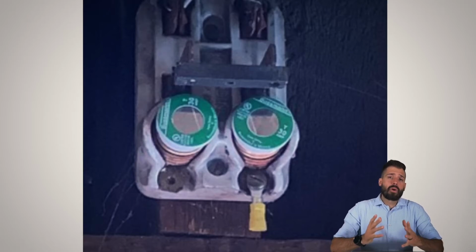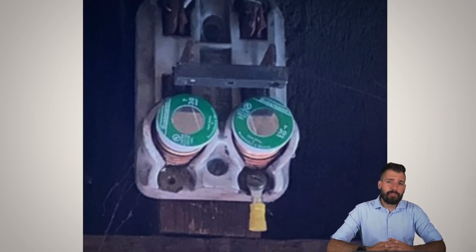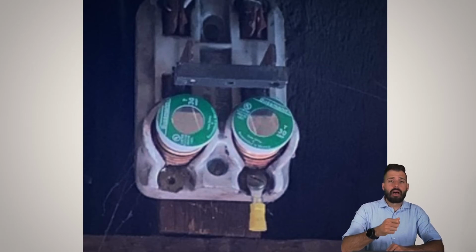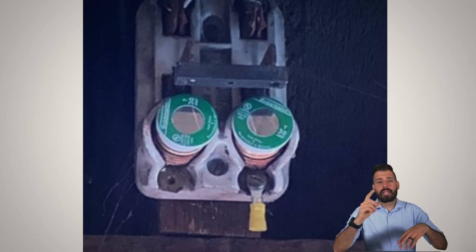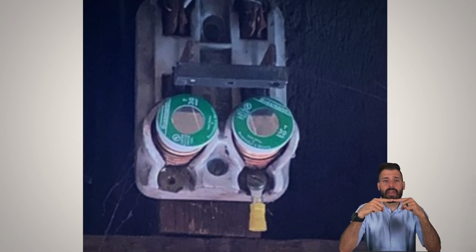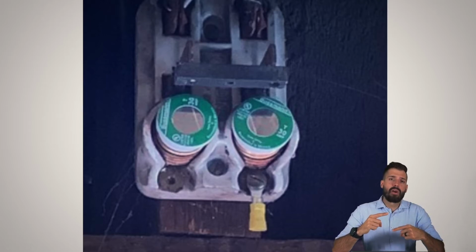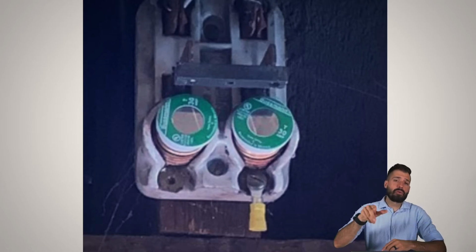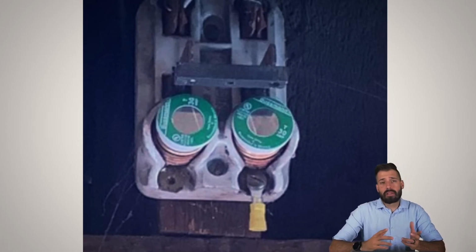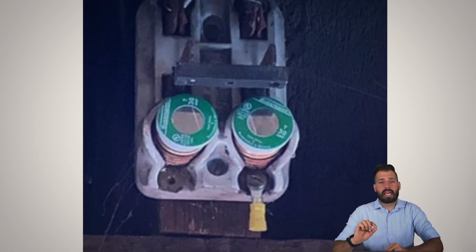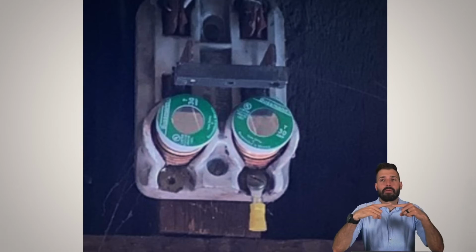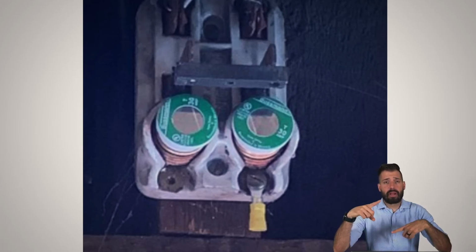With these fuses, the way that a fuse works, remember we were talking about a circuit breaker, it will shut off before any of the wires get too hot. Well, inside of here, you have a wire, and whenever that wire gets too hot, the wire will break. Whenever that wire breaks, you then have to unscrew, just like a light bulb, that fuse and then screw it back in. Whenever you do that, then we're good to go. So they've basically put a sacrificial piece of wire that will just break whenever it gets too hot.